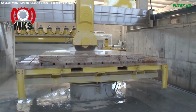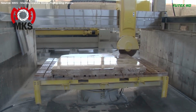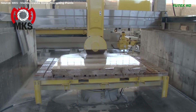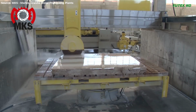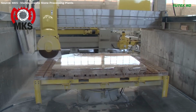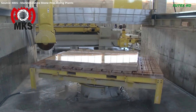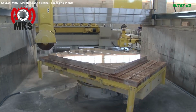This dual guide system ensures precise and smooth vertical movement, facilitated by low-friction materials. The screw nut mechanism, driven by gearboxes, allows the elevator to handle heavy loads with ease. Stainless steel covers protect the screws from contaminants, and lubrication windows simplify maintenance. A central automatic lubrication system ensures continuous oil flow to the hydrostatic linear guides, elevator slides, screws, and nuts.